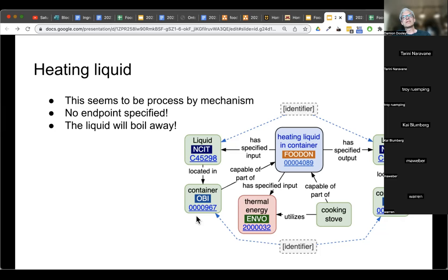As far as I can tell, there are a couple of kinds of objective. One is relative and one is absolute. When we talk about process by objective, we're using the absolute objective. By mixing some stuff, there is a relative objective happening, which is that from the last moment to the current moment, things are a little bit more mixed. Then I know my mixing process is working. The absolute objective is that we're mixing this to a certain viscosity, and now we need a sensor of some kind to detect that. A sensor might be needed just to know if our basic mixing process is working, with a relative goal. So that's talking about the objective at two different levels. Does that help? So mechanism still has some objective in it.